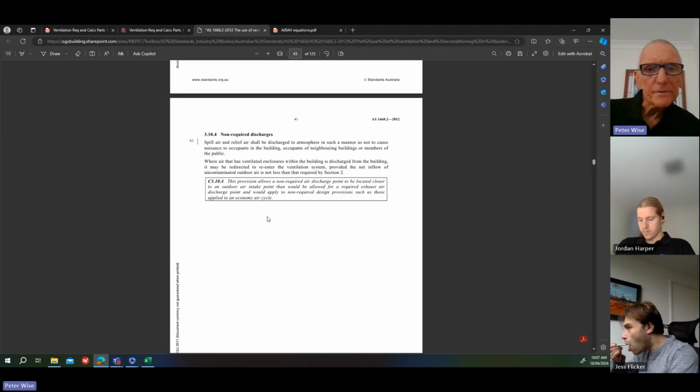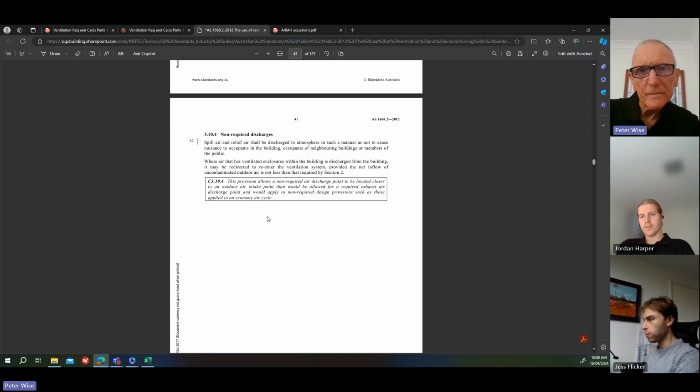If you bring in 100% outside air, you have to get rid of it. You can't just leave it there. It's got to be exhausted out or relieved out of the space in some way. The distance between the intake and the discharge in that case is not governed by the code because the discharge is not objectionable, and it hasn't got any smells in it. It's just hot air that you want to get rid of.